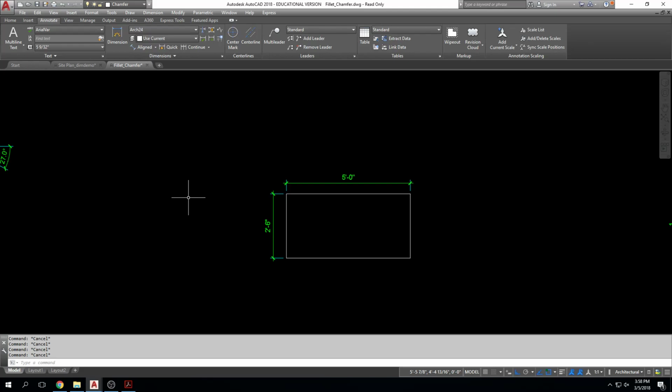But a chamfer that's maybe something like 50 feet may be more recognizable. You'll be able to detect it easier. So it'll look like something like that, instead of not looking like anything happened, okay? The same thing applies to a fillet, right? So a fillet is a rounded corner, but it's based on a radius. If this is, say, 100 feet by 50 feet, and I do a radius on my fillet of 1/4 of an inch, that little fillet will just be the tiniest little rounded corner right there, right?